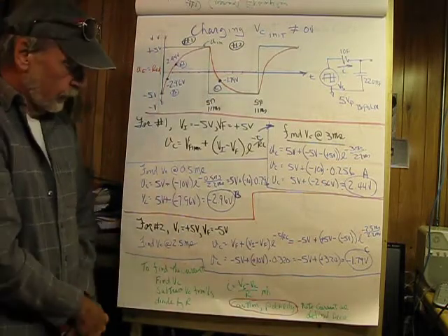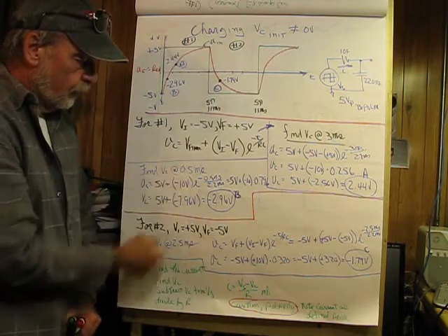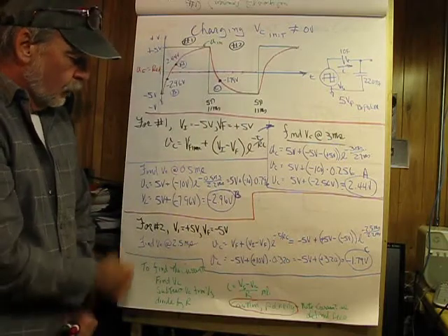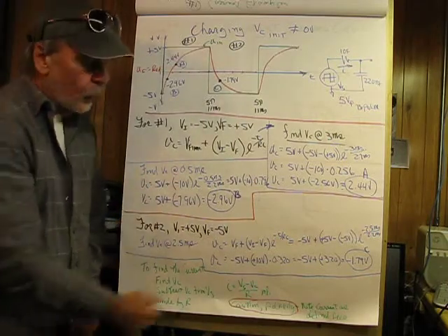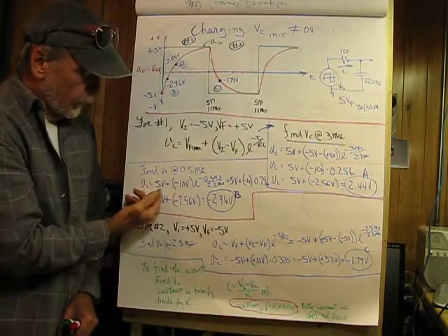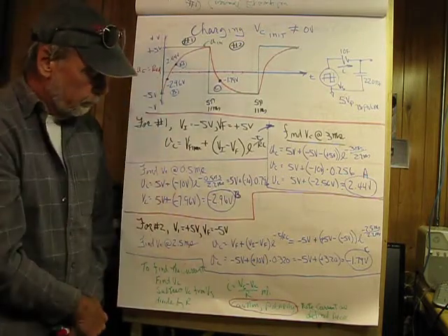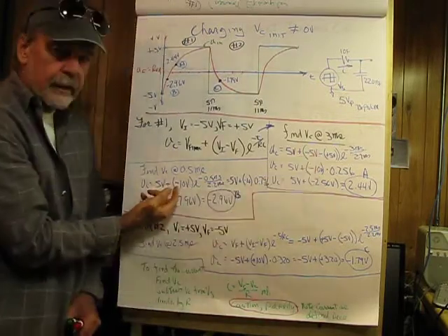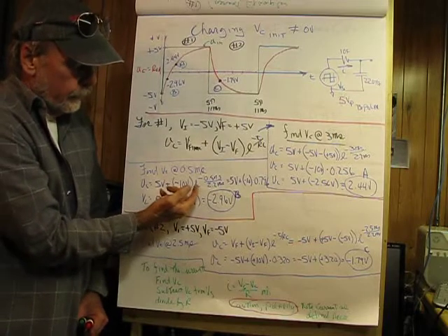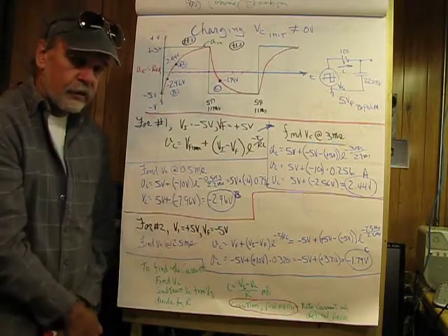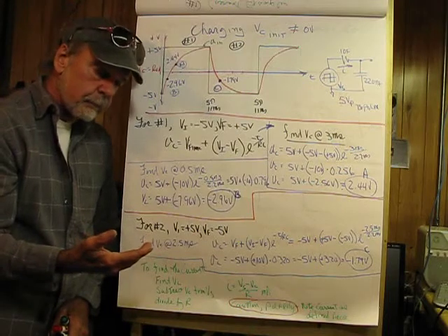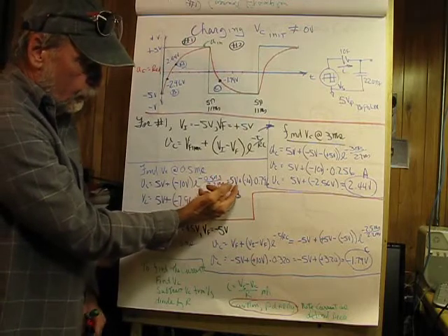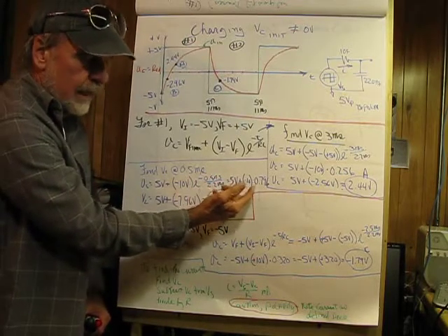Next example is we're going to find the capacitor voltage at 0.5 milliseconds, and again, this is in grouping A. So we'll just use what we already derived on this side. Our final voltage is going to be plus 5 volts. The component inside the parentheses here is going to be negative 10 volts. And now what I do is raise e to the negative 0.5 milliseconds divided by the time constant, which is 2.2 milliseconds. And that gives us 5 volts plus a negative 10 volts times